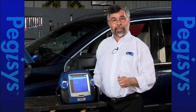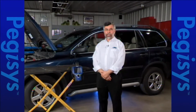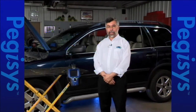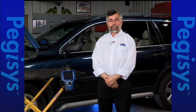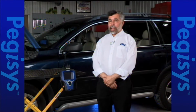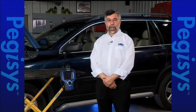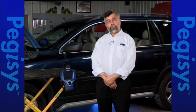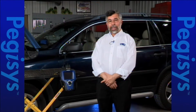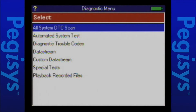Let's go ahead and do the same thing with the Genisys. Once again, let's perform the same special tests on our Volvo XC90. We're going to use the Genisys this time, but the difference you'll see is in the operation with the Genisys. The same tests, steering angle, yaw rate, and lateral accelerometer, are all located under anti-lock brake. I'm already at the anti-lock brake module testing procedures for the test menu for Genisys. So to begin our testing for calibration, we're going to scroll down to Special Tests.